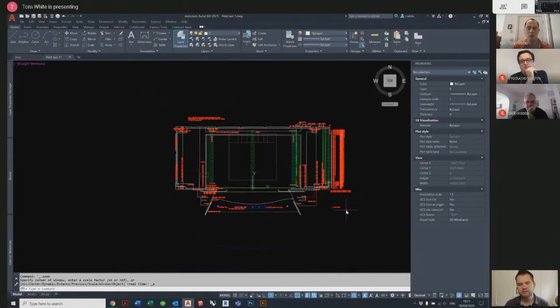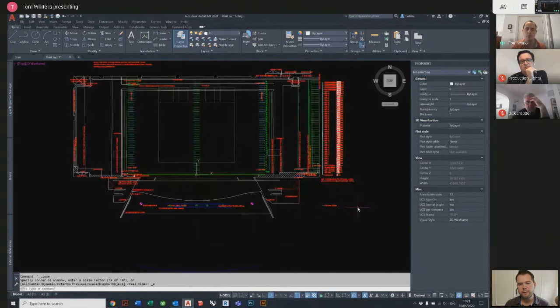And the reason is because it's difficult to replicate, because often the reason for printing a drawing is to ask somebody a question, and then for me to input their data, whatever that question is. Dave, could you tell me the size of the stage trap? Or Dom, could you tell me the position of the lights? And then they want to have that replicated. So in my opinion, the problem of printing the model space is it's not very easy to replicate exactly what you've just done. That's where layouts are quite good at replicating it.